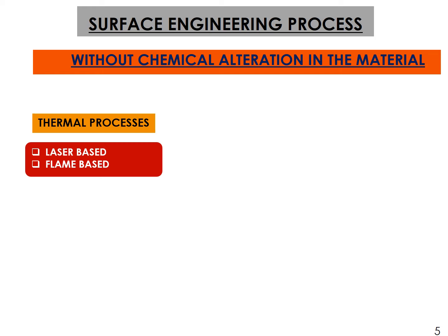While applying this laser to material processing, we can further classify it. As an example, suppose you want to change the microstructure of a small area of that surface. That's one category. There we can use limited energy of the laser to cause that change. But if you want to change the state wholly, if you want to carry out some phase transformation for large areas, then we have to increase the amount of power involved. So likewise, it has been categorized. So with laser, we can modify the properties of the surfaces.